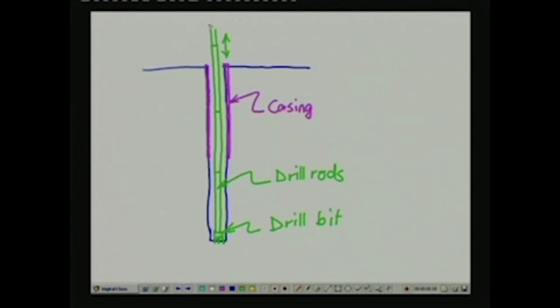It is not done in a very regular manner, and then there is a handle near the top of this particular drill stem, and this is called the tiller, and this tiller actually is rotated back and forth in the horizontal plane as I mentioned earlier, and these rods are in a sense hollow near the center, and through the center of these rods a drilling slurry is circulated,